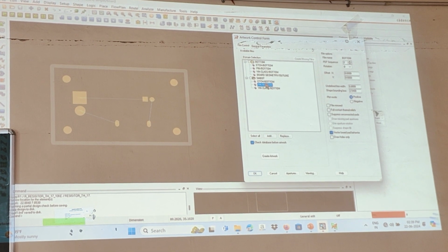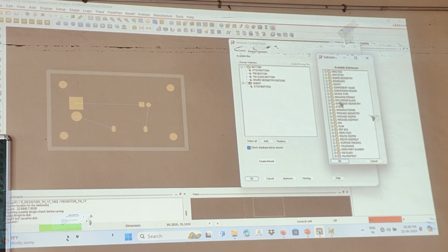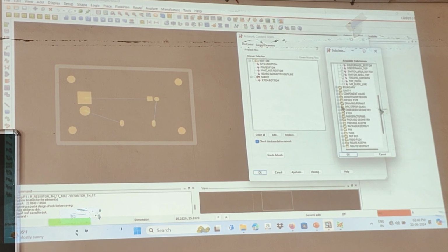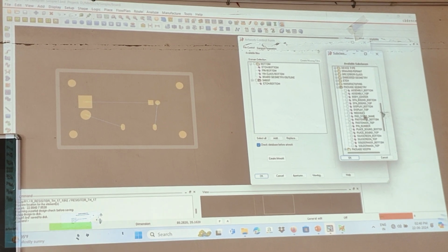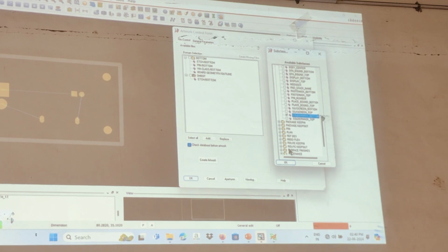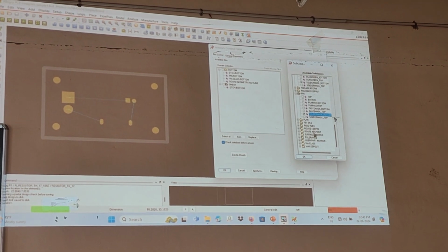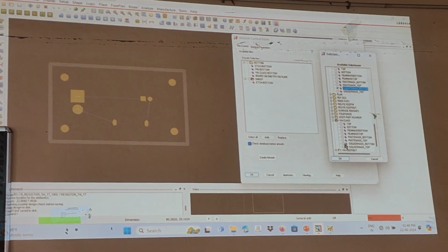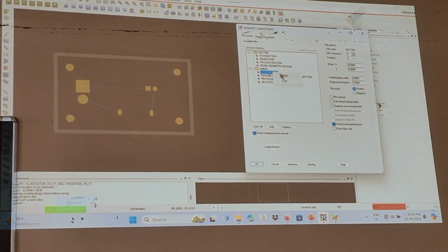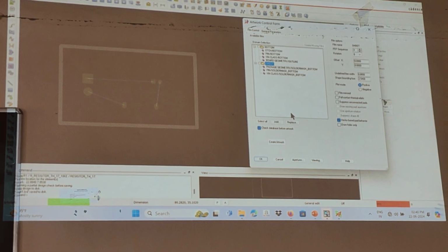In that we have the unwanted classes and subclasses. Here in the SM bottom we need to add board geometry, outline, package geometry, solder mask bottom, and pin, solder mask bottom, and wire class, solder mask bottom. Then click OK. We have no need of etching part in this SM bottom layer, so cut it off and display for visibility.